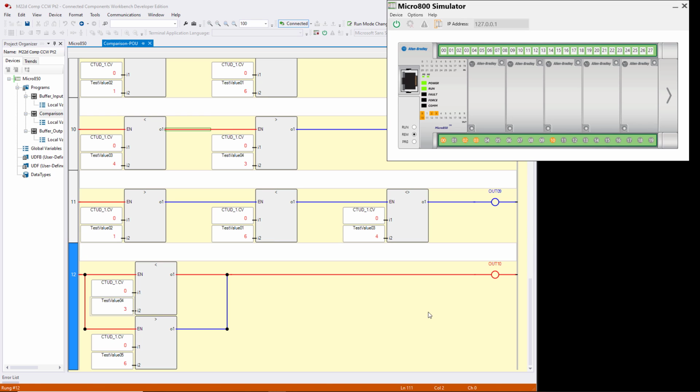So if we look at rung 11, we have if the count, which is now 0, is greater than 1 and less than 6 and not 4, then turn on output 9. So as we count up, and I want you to pay attention to, in the book it'll say, did adding the not equal with a test value of 4 change the result? Yes. Which values of CV will render the rung true or output 0 in the on state? So as we're looking at output 9 here.